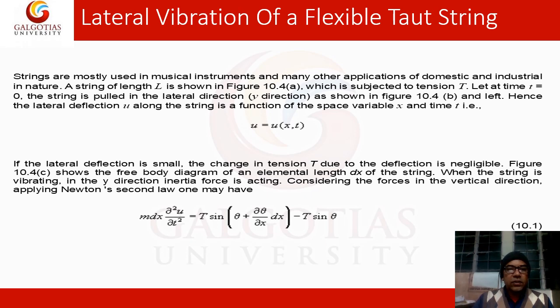If the lateral deflection is small, the change in tension T due to the deflection is negligible. The figure of that is given over there. This is the free body diagram of an elemental length dx of the string when the string is vibrating in the y direction; inertia force is acting.